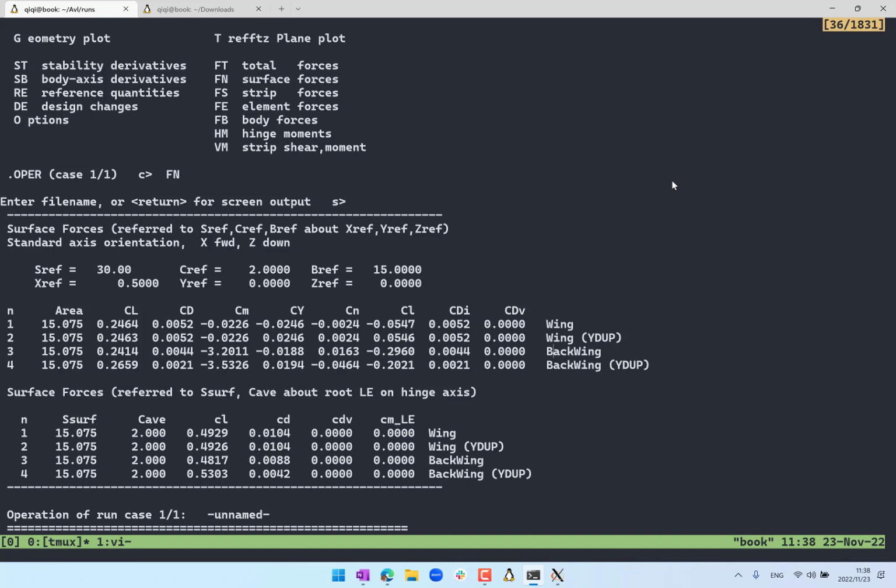of course the lift on the duplicated back wing is now a lot higher, and look at the induced drag, right? I mean, both induced drags are reduced, and the side of the wing that's closer to the tip vortex has the induced drag reduced by more than 50%, right? Okay, so this is a way you can calculate the whole induced drag of the formation flight. And I need to look into how you extend.